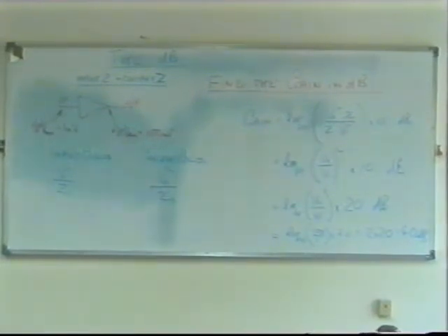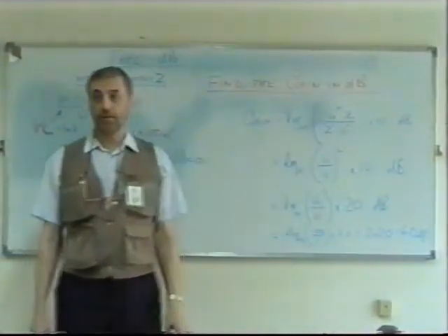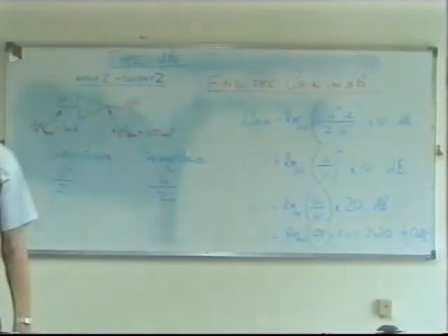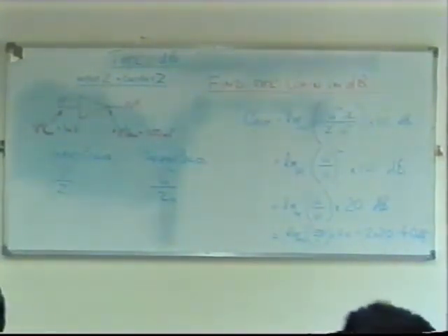Okay, so we've done the decibel, the dBm, and we've been able to find the gain using a voltage ratio if we didn't know the power ratio. We should know that if we attenuate a signal, that means we have a negative value of gain, a negative dB.